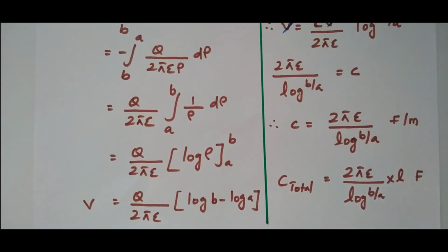So in this video we discussed the cylindrical capacitor and its derivation. We got the expression for the capacitance of a cylindrical capacitor, which is nothing but an underground cable. We got the expression for capacitance per meter as well as the total capacitance.